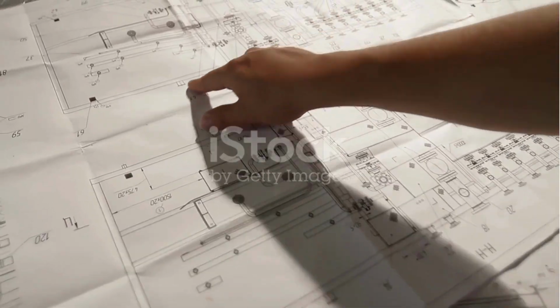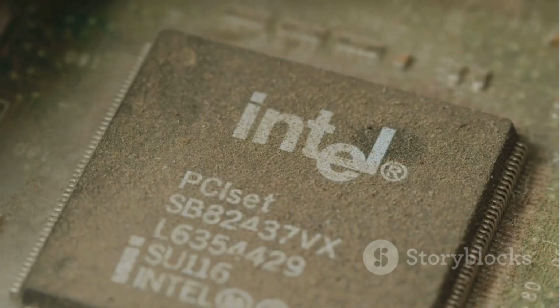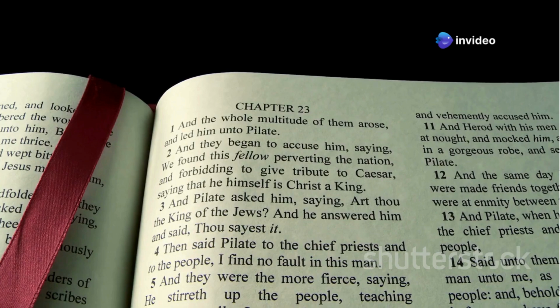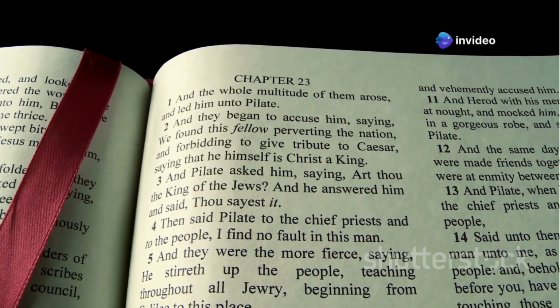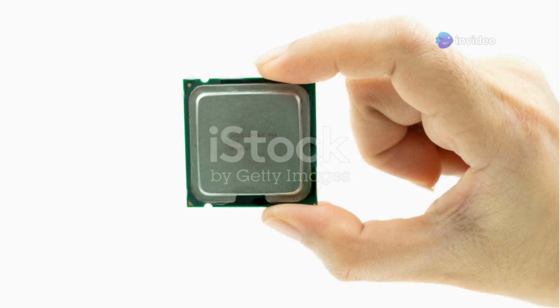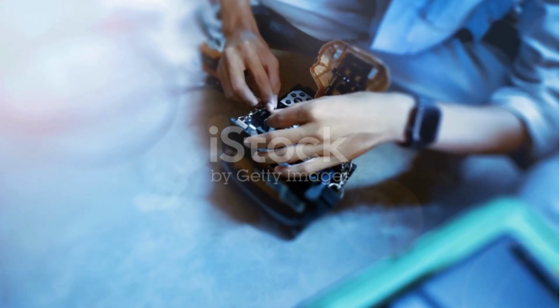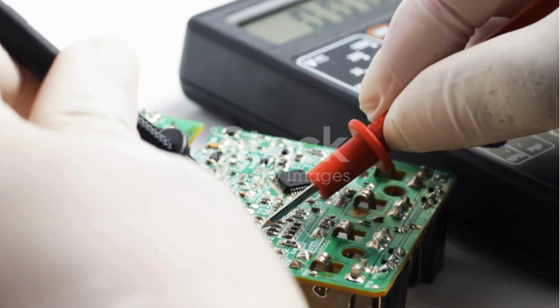Now let's dive into the basics. Start with the title section. This typically includes the component's name, part number, and a brief description. It's like the cover of a book, giving you a snapshot of what's inside. Next up, the pin configuration. This section shows you the layout of the pins and their functions, crucial for making sure you connect everything correctly.